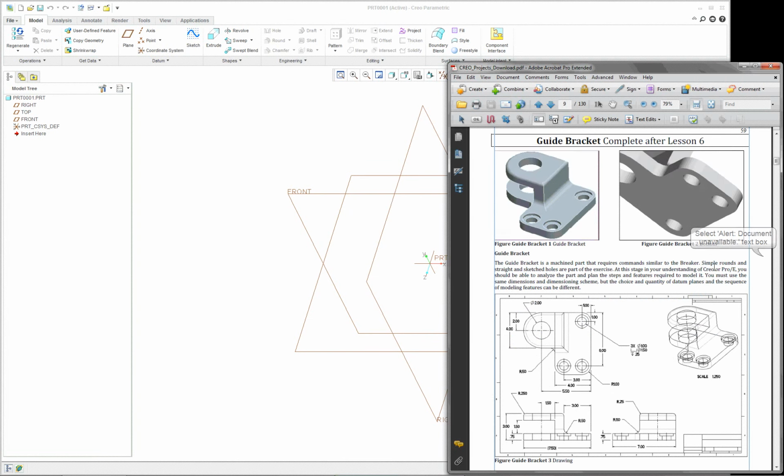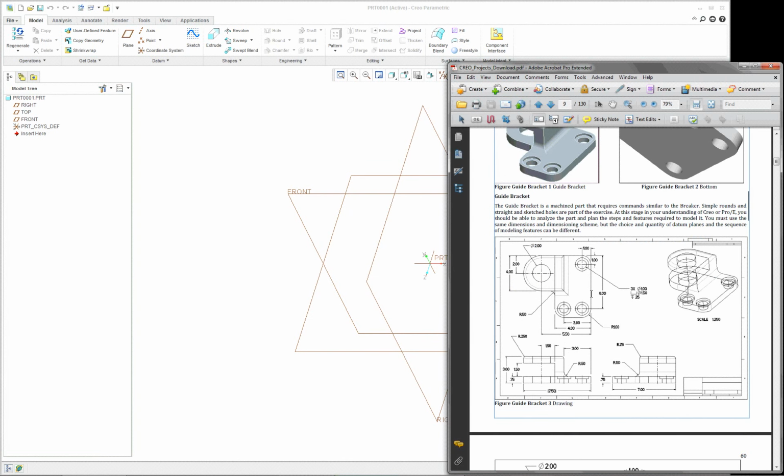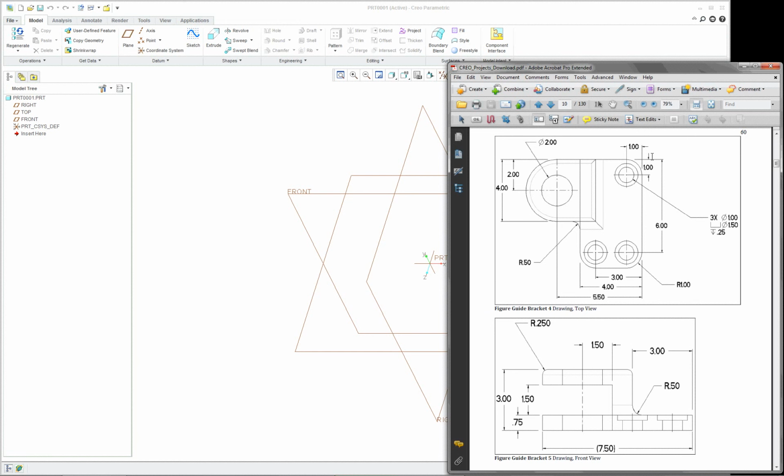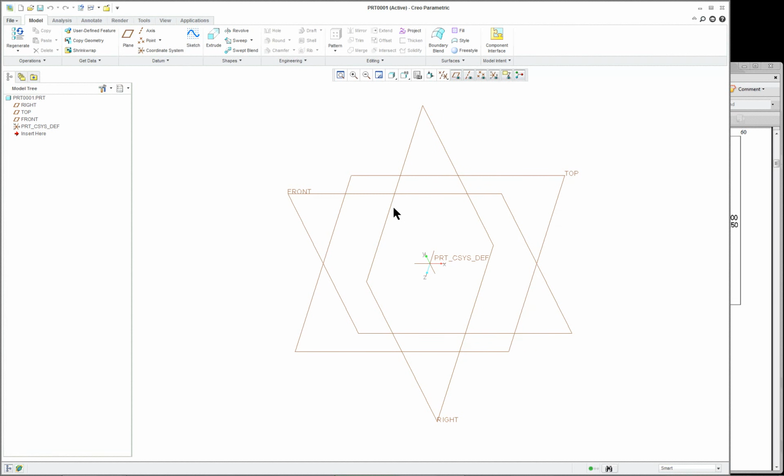And when you look at this particular project here, you're going to notice that it has two flat sides. You want to place the section so that you can use either of these two sides as datum B and C. Datum A will be along the bottom of the part. So whenever you're positioning a part with any CAD system, you want to establish how you're going to sketch it based on the geometric tolerancing of the part. So our purpose here is to take this surface on the side here and the one across here, we'll call it the top, and position it so that it goes into your sketch correctly.